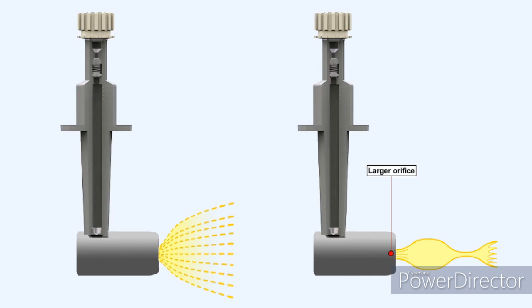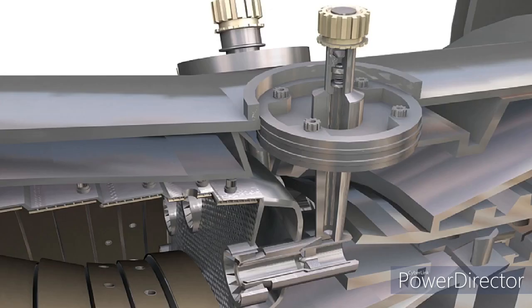Thus, for that type of situation, other methods must be found to sufficiently atomize the fuel at engine start when fuel pressures are low. The airspray system uses a high-velocity airstream to break up the flow of fuel. It requires only relatively low fuel pressures, and can therefore operate using the gear-type pump, which is much lighter than the more sophisticated plunger-type pump.